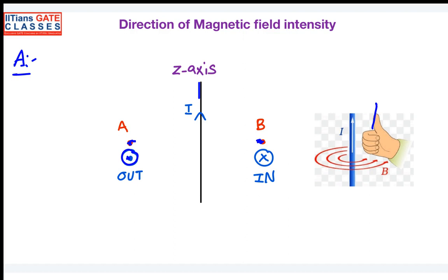Right. So the magnetic field intensity is only the measure of how much magnetic field is existing at a particular point. In order to define the magnetic field intensity, you can make use of the Biot-Savart's law. The Biot-Savart's law gives the differential magnetic field due to a small current element, and you can integrate the differential magnetic field to get the total magnetic field due to the full length of the wire. So that is a concept you have seen till now.